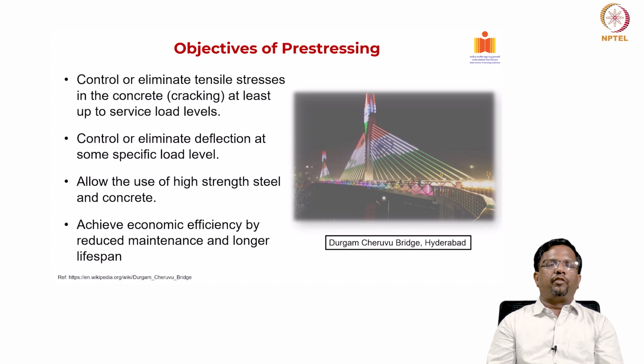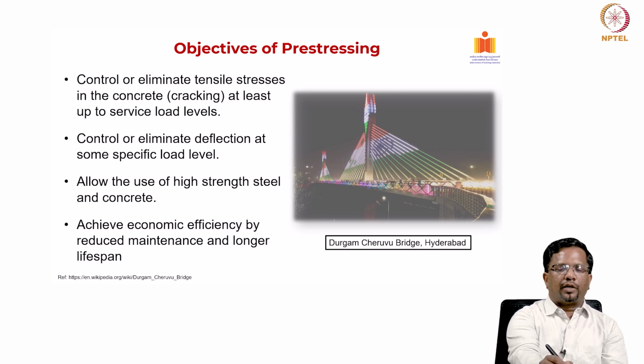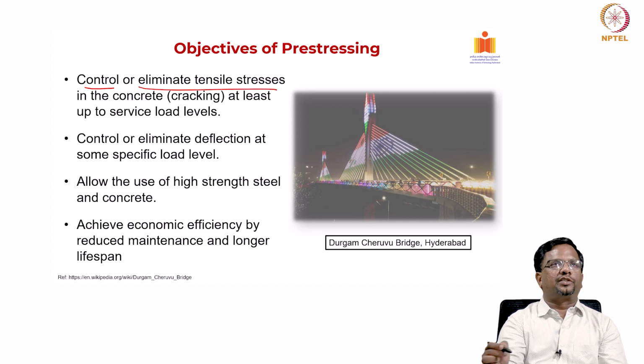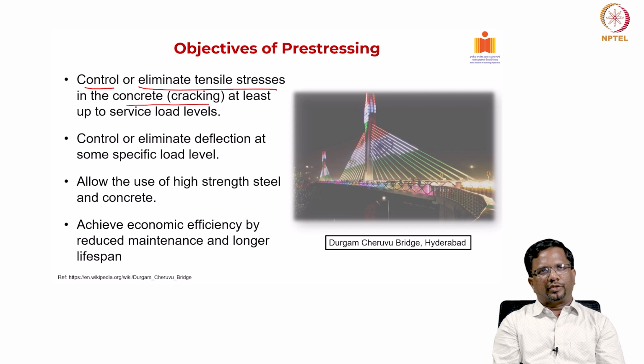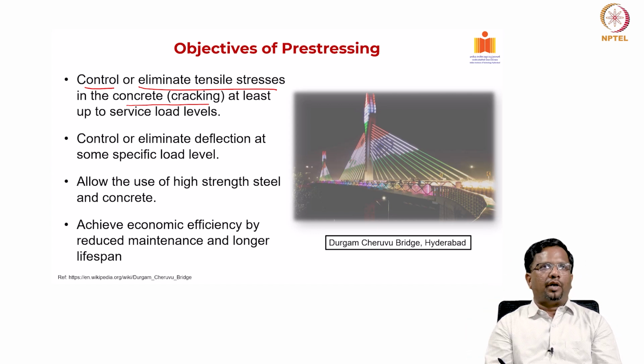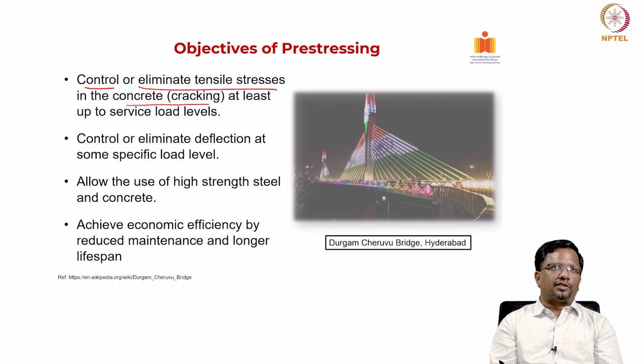So, our idea of pre-stressing is to either control or eliminate the tensile stresses in the concrete, okay, at least under service loads. Of course, when the load levels get higher, to the level of ultimate load, then the element has to crack. But under service loads, we want to make sure that the tensile stresses are kept to a minimum, so that they are not going to crack.